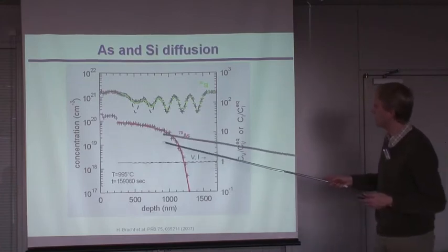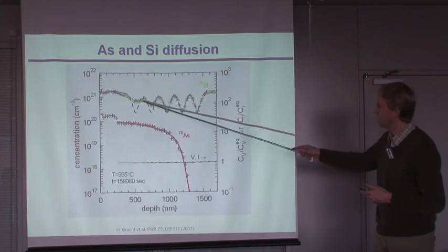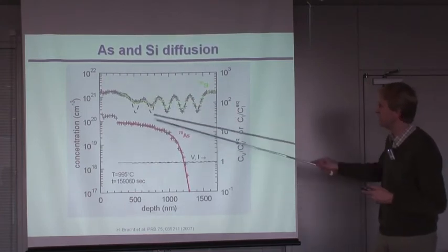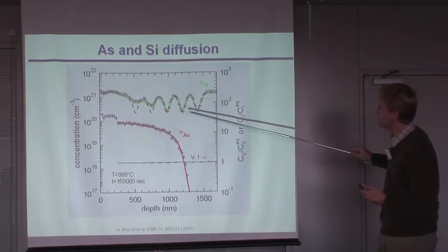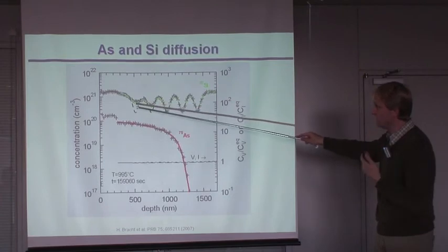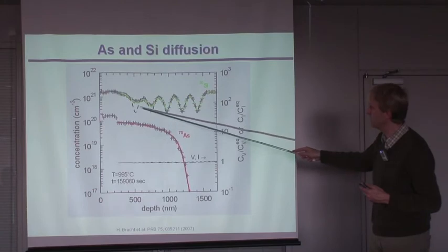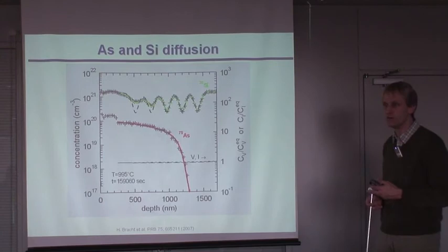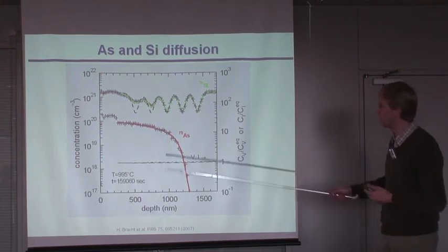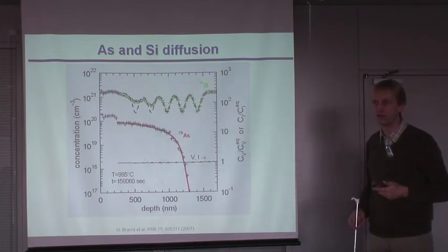Yeah, and now of course in the fitting of these kind of diffusion processes, you have to do the modeling of both the self-diffusion and the dopant diffusion. And here you can already see, based on the broadening here, it's more pronounced than here, that the native defect must be negatively charged. So here the dashed line is shown, which shows a homogeneous broadening. What you would expect if all native defects would be neutral, then the broadening should be homogeneous. So you can say directly, okay, there must be a native defect which is negatively charged.